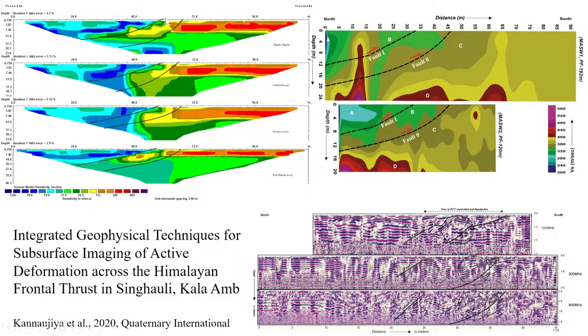Clearly you can see this is due to the lithology change, because this tertiary mainly has sandstone and conglomerate. All these formations mainly have sandstone, because you get the middle Shivalik here, and this quaternary mainly has alluvium. So you can see this is the alluvium, and the whole of this is the tertiary formations, and you can see this truncation and the sharp contrast in the resistivity.